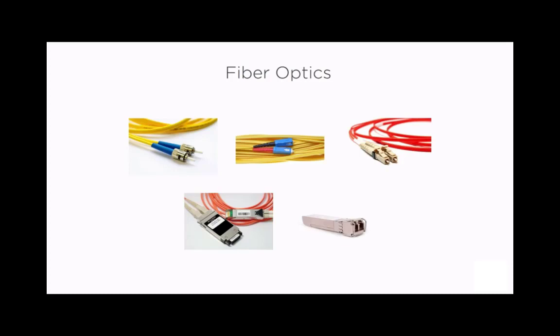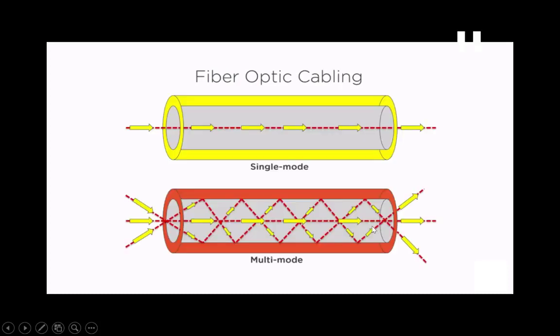For connecting the fiber to the switches or any other devices, we use hardware which is called an SFP. As you can see at the right bottom side, we have an SFP. We can plug the connector of our fiber optics cable into this SFP, and this SFP is inserted into our switch or router or whatever device we have for communication. So this is the fiber optics.